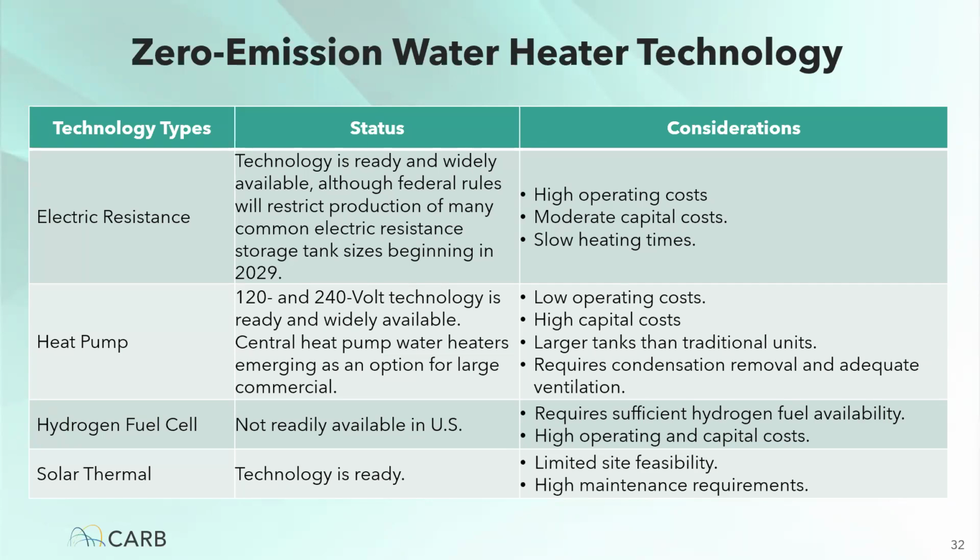The emergence of 120-volt products can serve as a solution to reducing panel capacity concerns for retrofit applications, and the development of central heat pump water heaters is expected to increase uptake of heat pumps in large commercial buildings. Split system heat pump water heaters are also emerging as a solution for space-constrained applications. Heat pumps tend to have high capital costs, but low operating costs, and capital costs are expected to decrease for these technologies as adoption rates increase. Heat pump water heaters also require larger storage tanks than traditional units and may need condensation removal and ventilation.